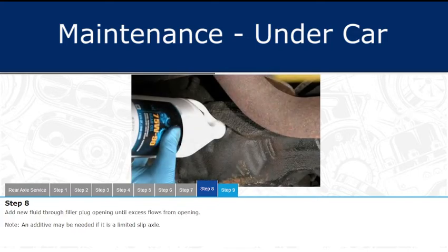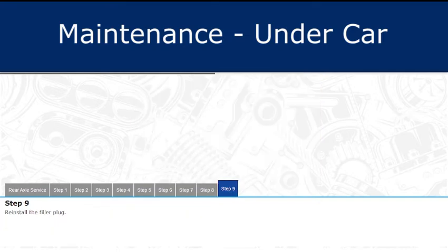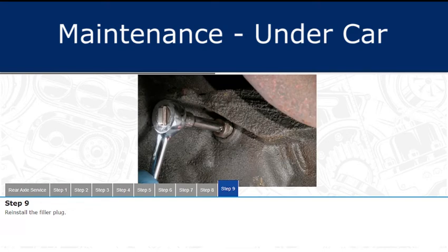Add new fluid through the filler plug opening until the excess flows from the opening. Note that an additive may be needed if it is a limited slip axle. Reinstall the filler plug.